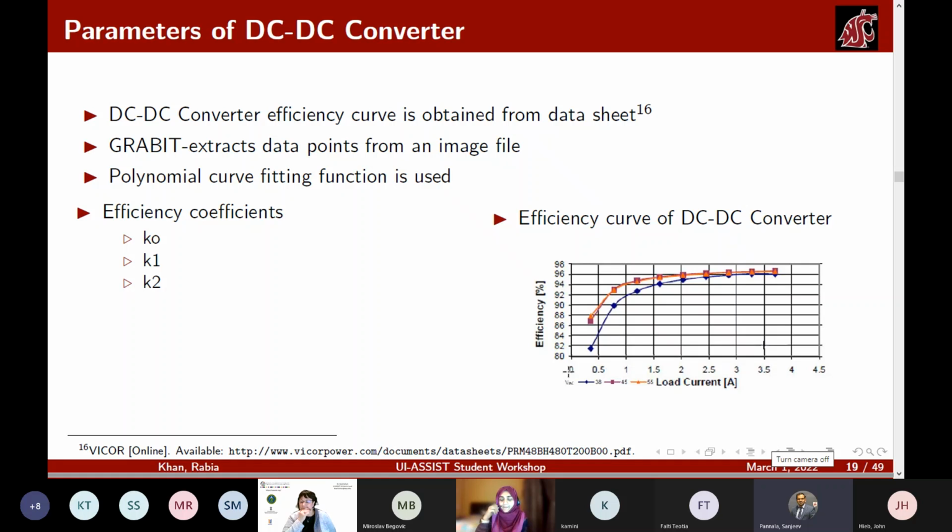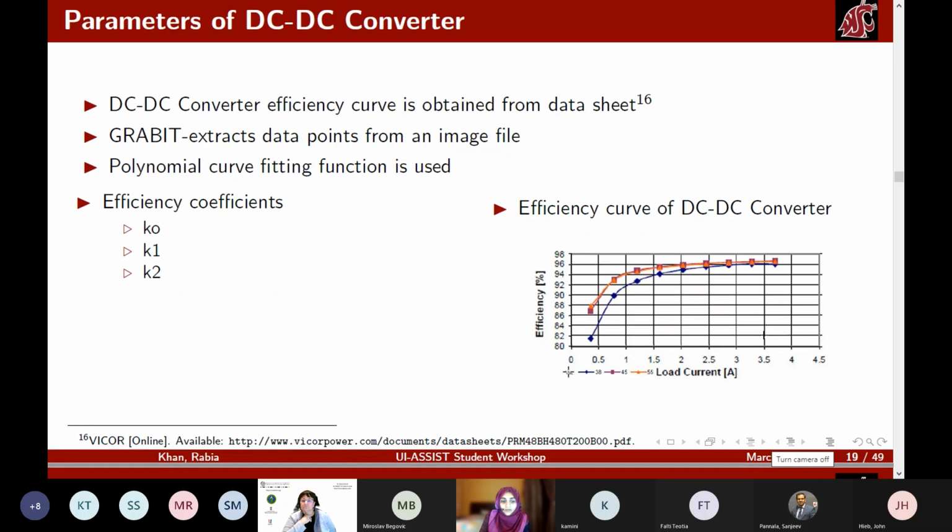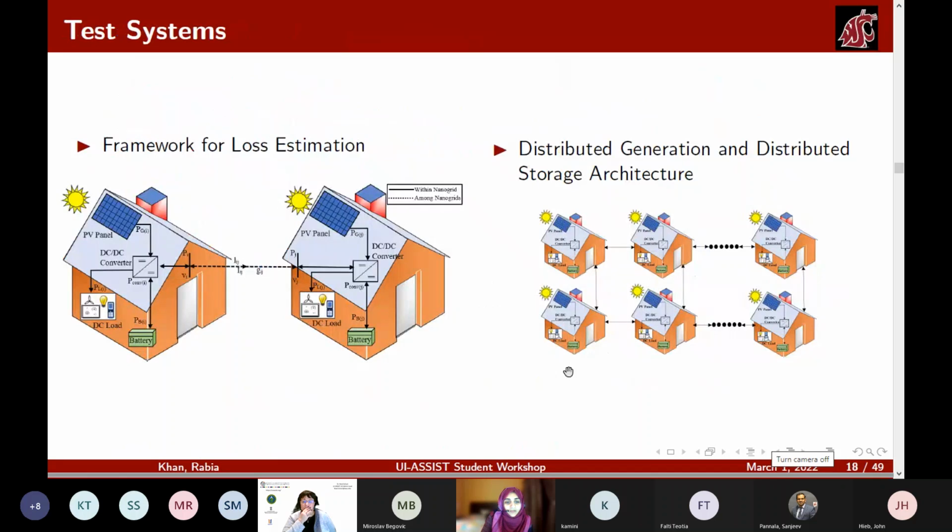One question I have is that because you consider these DC-DC converters connected to the PV, how do we always operate at a maximum when there is no PV power input? So actually we consider both PV and battery; this converter is for both. When I considered the parameters, we chose them in such a way that the batteries are of higher rating, so that when PV is not there, they should be able to meet the load demand.